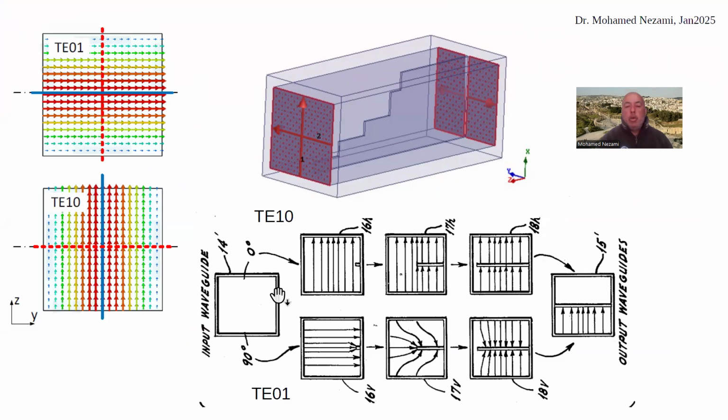So we've got a square waveguide on one end, which is coming from the horn antenna, or a circular waveguide. And we've got either the vertical or horizontal components, depending on which one is 90 degrees from the other one. You basically get the signal coupling into two separate paths. You can see that here.